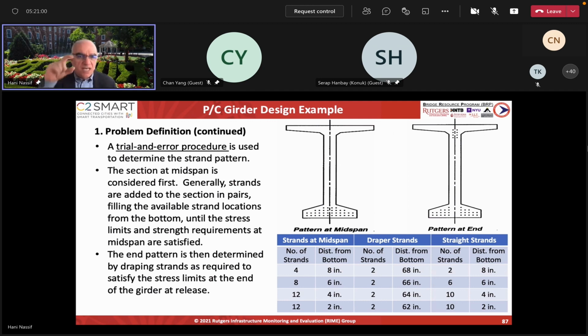Spacing between the tendons everywhere is 2 inches, because this is the standard distribution that the pre-stressing plants have. When you want to order these girders, they have these holes spread at equal 2 inch spacing. So you don't want to try to change that because that's not possible.